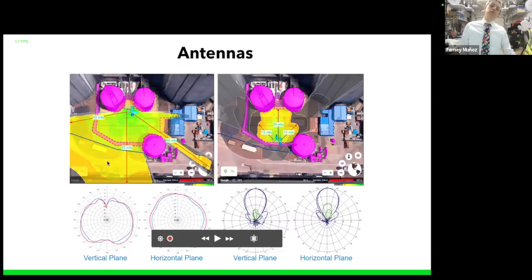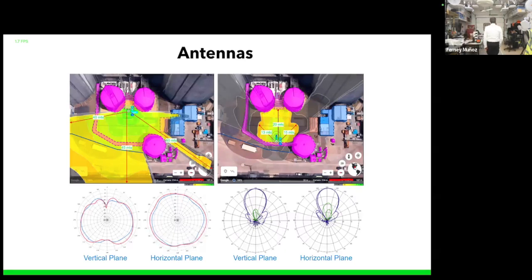But then you're also covering areas you don't want. You don't want to cover out there. So in that case, you'll just use a semi-directional, like here, shooting for the area you want, without covering areas you don't want. What's the deal with that? In Wi-Fi, antennas will transmit waves only when there are no other waves in the air. So if I hear someone over there, I will not talk. We'll get to another one, and I'll explain this in a little bit.